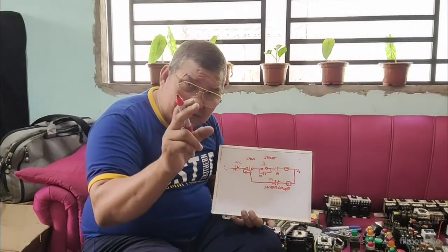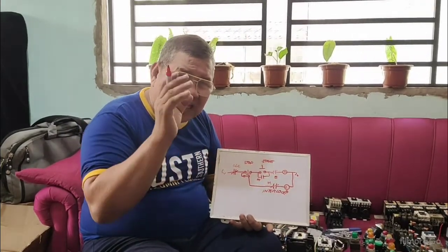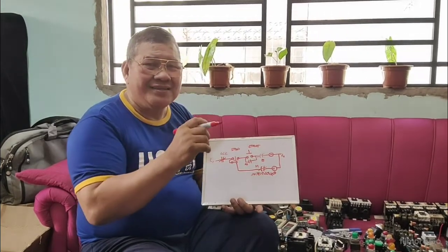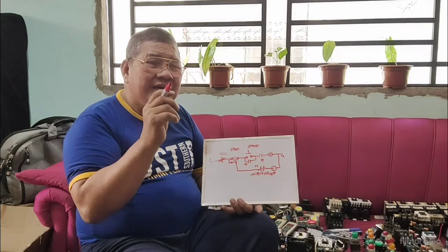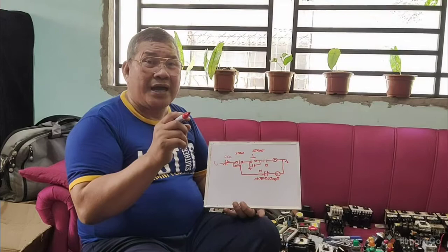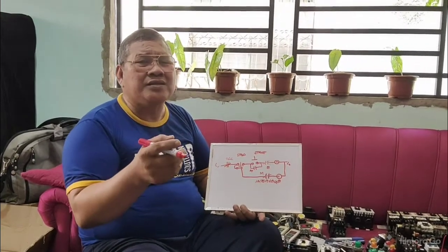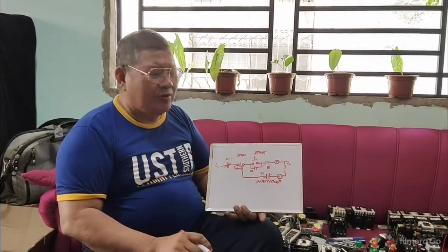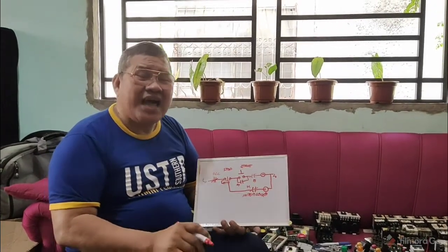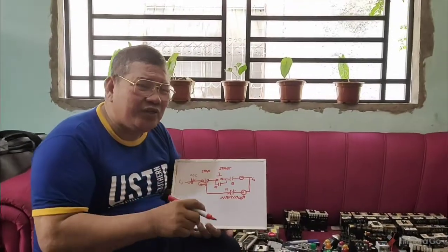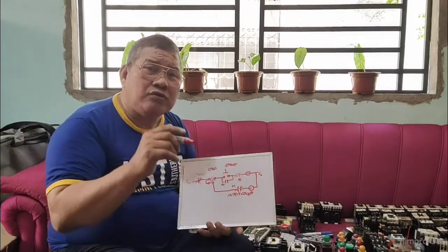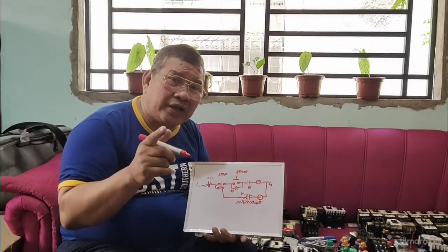Don't forget, the DC will not exceed the 220 volt AC. Half of that, 110, is enough. Anyway, the DC will energize one phase for a short period of time, maybe 1 second or 2 seconds, enough to stop the motor quickly. So again, it is nice to connect that in actual so that you can really observe. But don't worry.